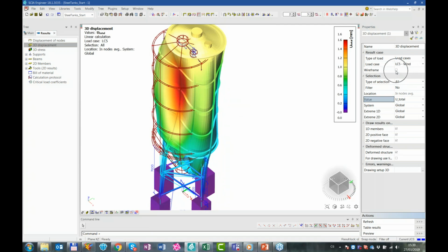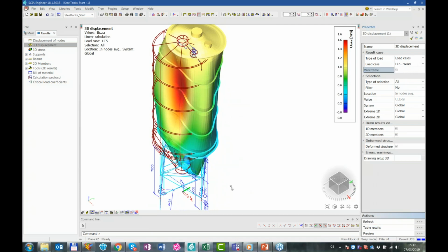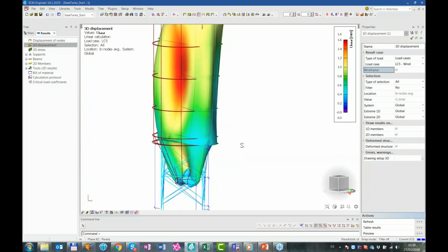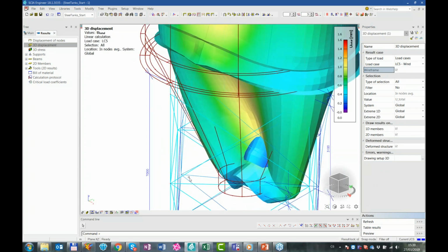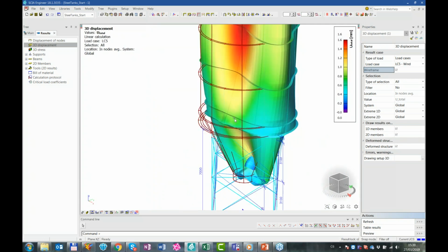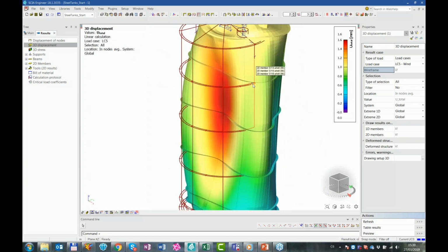However, if I use the wireframe option here and I hit refresh, you can see that I see the results basically instantaneously, because beams are now represented by only single lines, and the shells or 2D members are represented just by their single structural plane.